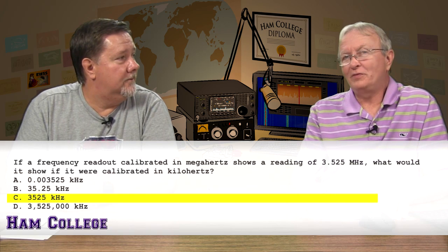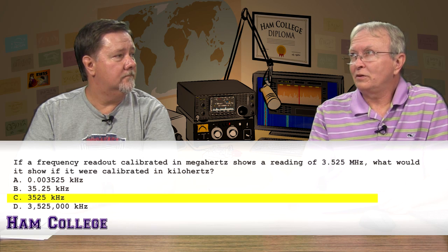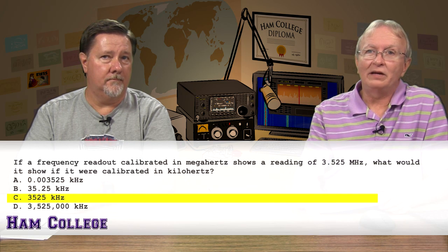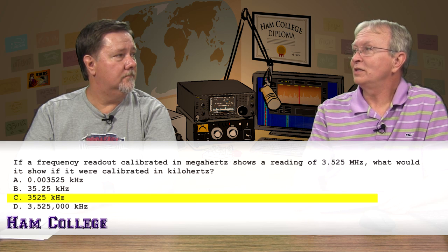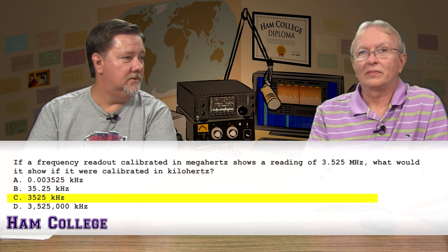You also often hear people talking about HF frequencies. You might be on, say, 3847 kilohertz. That's 3.847 megahertz. If you're looking at your radio, it's going to say 3.847. Yeah, but most of the time they don't say it like that. No. I'm on 3862 or whatever, and you just do it in your head. Most folks just give it out in kilohertz. I'll often do it in megahertz, though, for whatever reason. You can do it either way, though. But be sure you got your kilohertz or your megahertz right, or there's a big error there. Yeah, but if you're on the right band, you'll figure it out pretty fast.